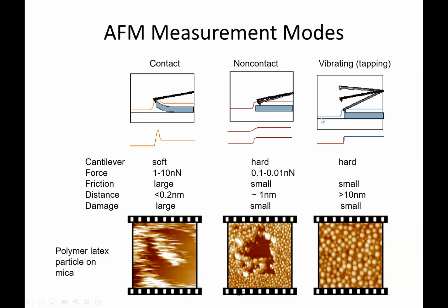The other one is the vibrating, it's tapping. Having the tip on this surface by tapping very often, then we can have this surface information. So each one has pros and cons. This can be used for very steep surfaces, and also some large surface areas, not much affected by the surface material, but with some limitation for sticky materials.